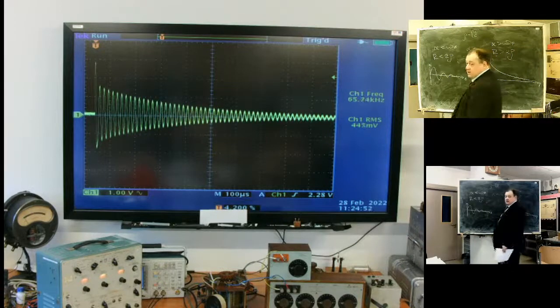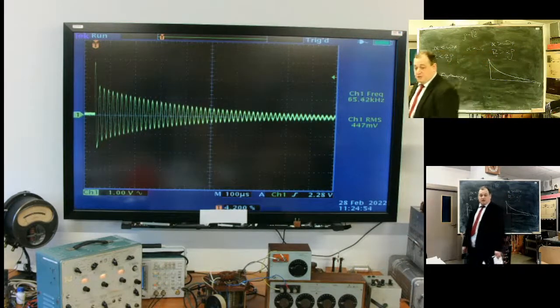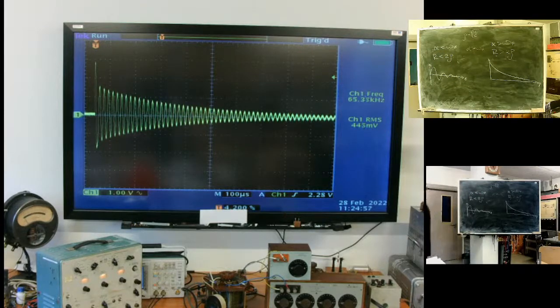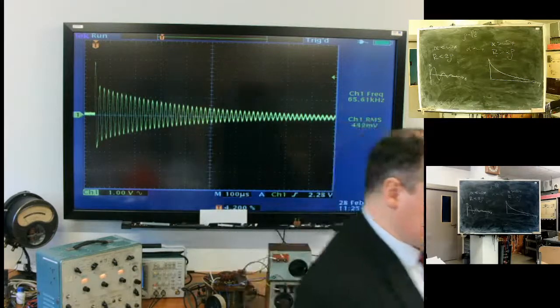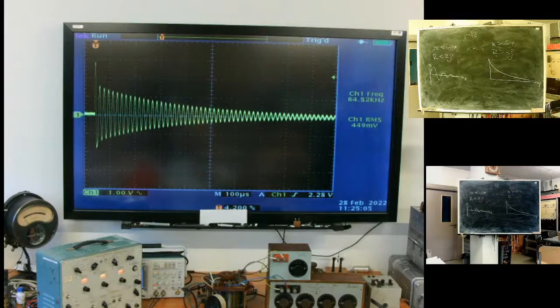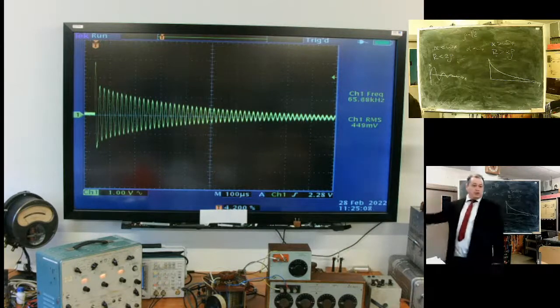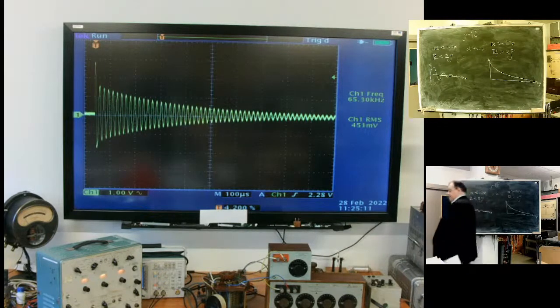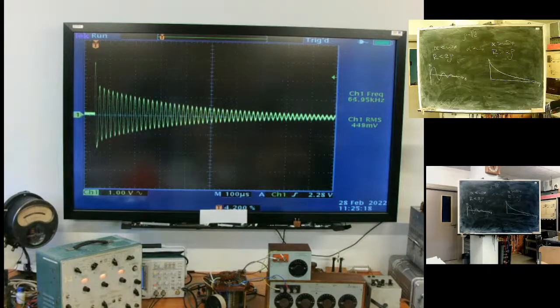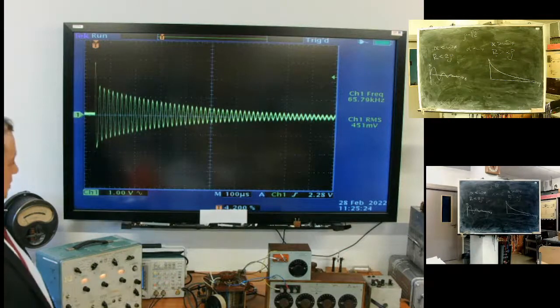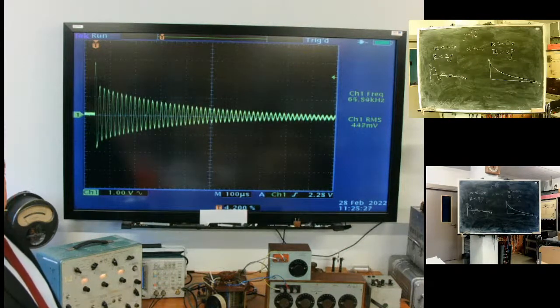If you have some kind of inverter and you get a process like this, your semiconductor switch will not last, because the high frequency component of oscillation causes hot spots in the structure of the semiconductor element, IGBT transistor or whatever, and fast degradation.